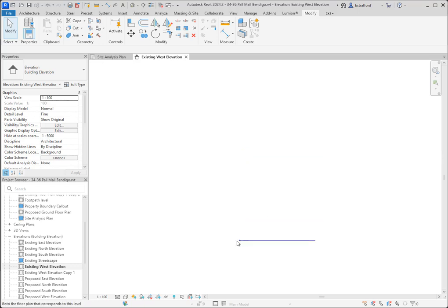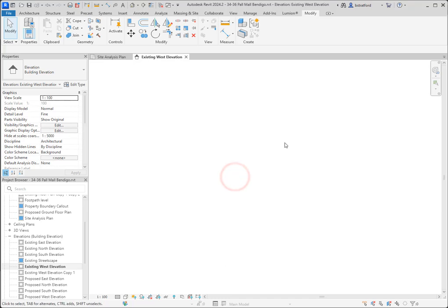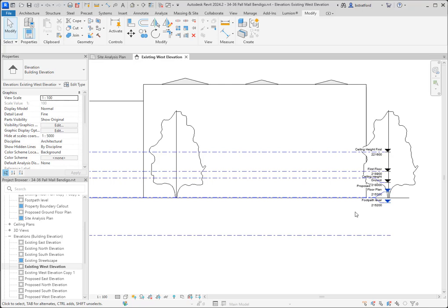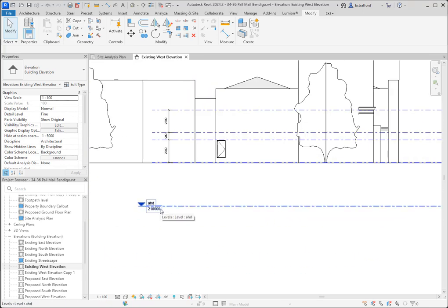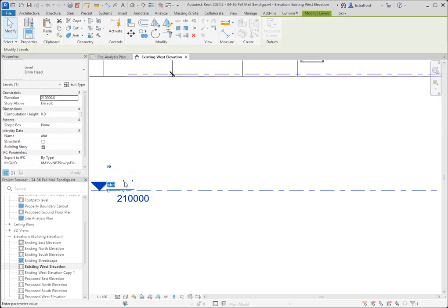It'll create a solid topography, a solid Toposolid all the way from that point all the way up, so it's probably a little bit heavy. So what I'm thinking is maybe 210. 210 is going to sit below. I've got 215, so it'll make it 5 thick, and we can change that at any time, and I'll rename that to topographic.